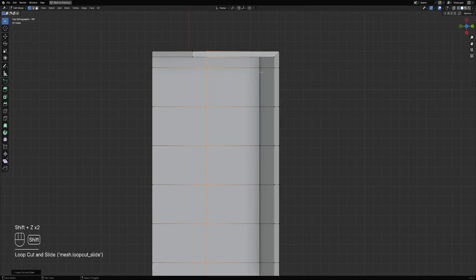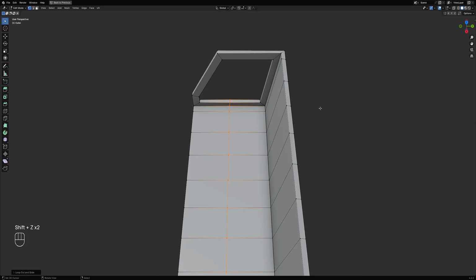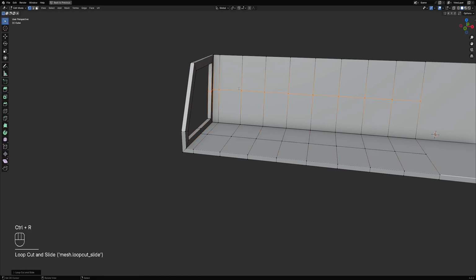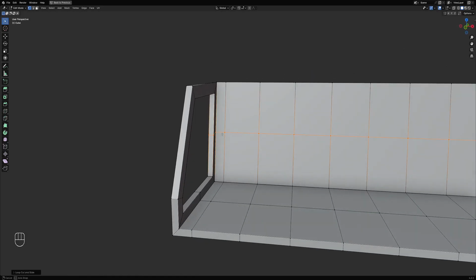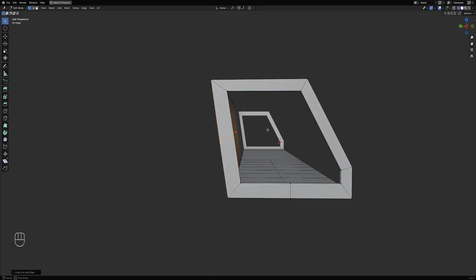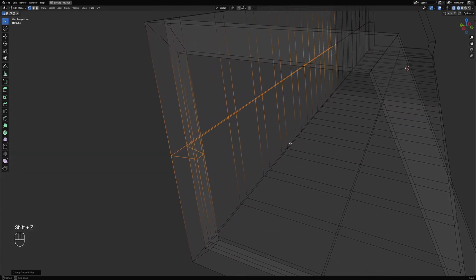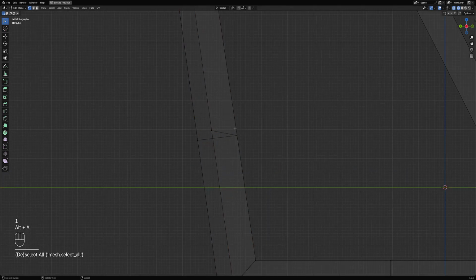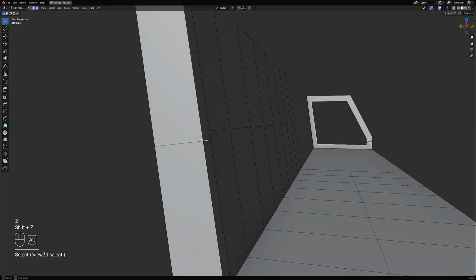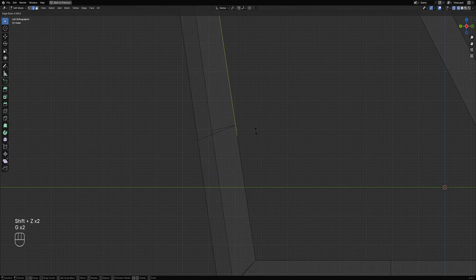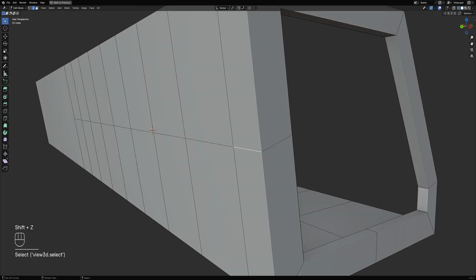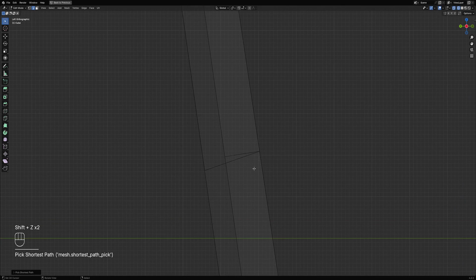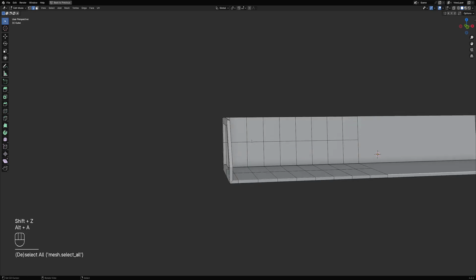Let's make it straight in the y-axis, scaling it to the y-axis, and just press 0. This one here, we can't use the z-axis to straighten this, but you can just probably eyeball this. Selecting this edge here, press GG to slide the edge. There we go. And then bevel.